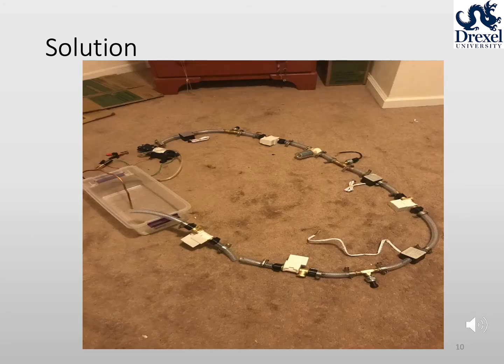This prototype has inlaid sensors for temperature, pressure, and flow rate. There were also servo-operated shutoff valves in place to replicate blockages and leaks to test our system and to make sure it could detect those issues accordingly. The physical system was a continuous flow line that consisted of a sump to a pump, to a filter, to a heat exchanger, to a load, with sensors laid out in between the necessary components.